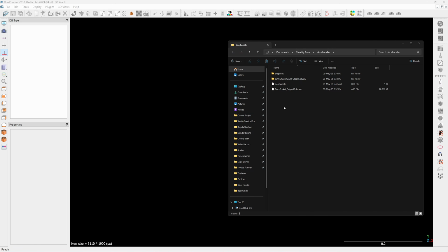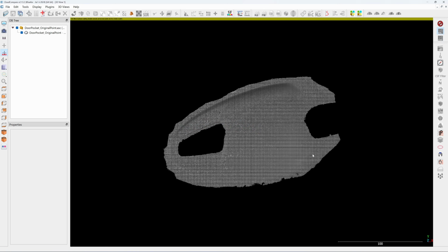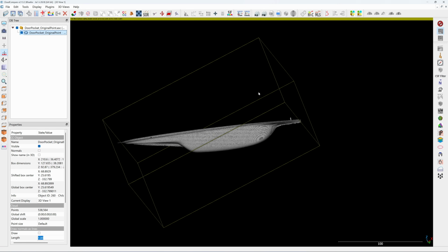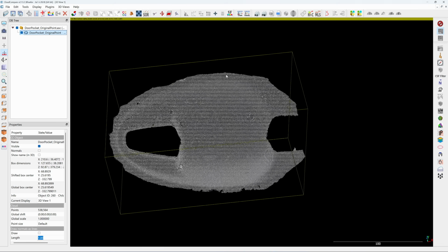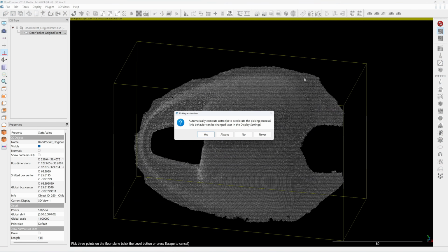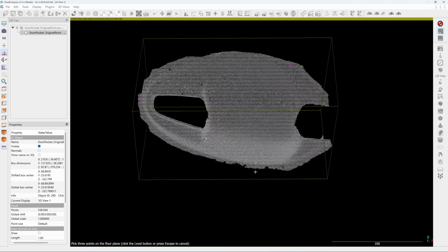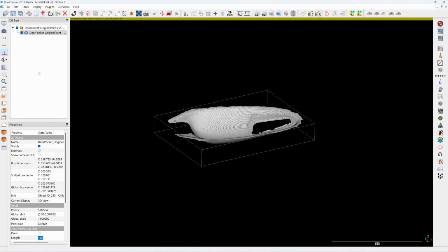Okay, here's in cloud compare. I will drop the point cloud from the Creality scan. Click on EDL. Because this is a car body part, it's the panel of the door, so there is no flat plane anywhere. So I would just make it easier for me to trace. So I would just pick 3 point and I will flat this onto the XY plane. Okay, now it's flat.